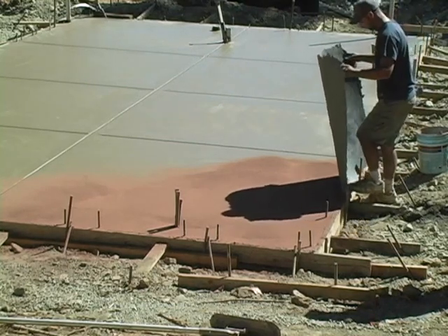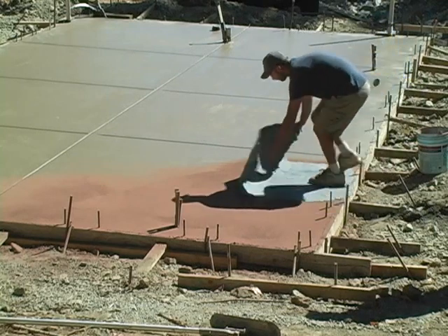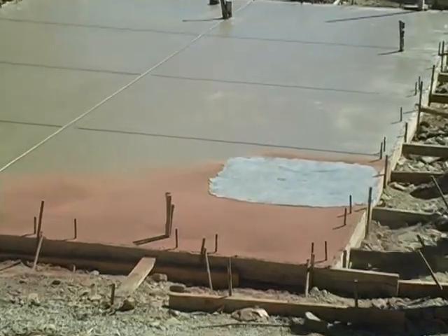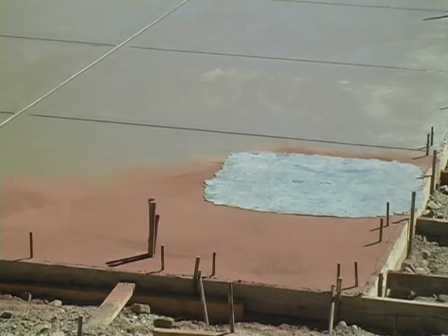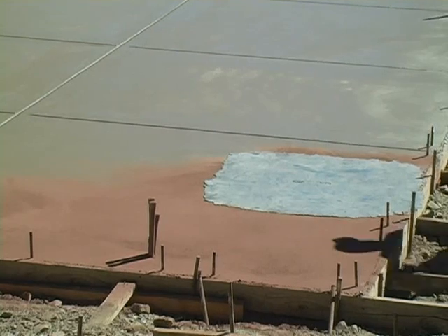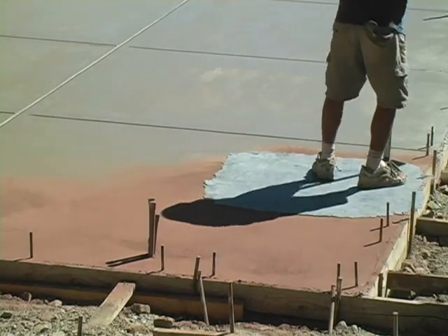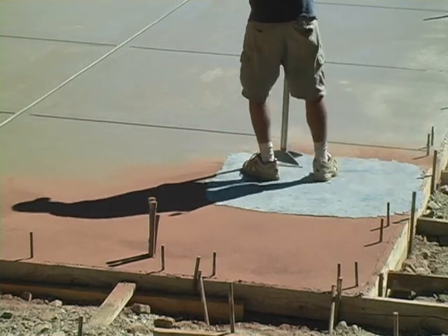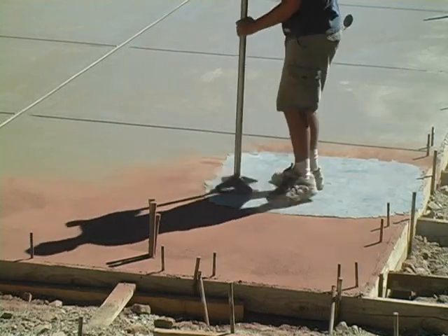So here we'll lay one end down where we want it, roll it down into place, and once it's in place, then we can use a tamper to tamp that pattern that I showed you earlier on the stamps themselves. Use a regular tamper to imprint the surface of the concrete. One thing that's really important with the tamper is that you hit straight down. If you hit the stamp with the tamper at an angle, you'll rip right through the stamp and ruin the stamp. And these are not cheap.